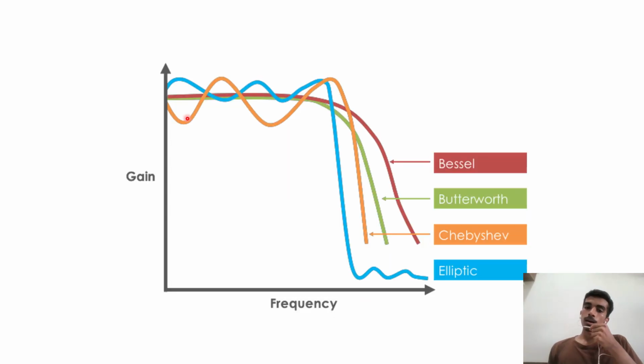As we said, Butterworth filter, why not use Bessel? We all know both Butterworth and Bessel have a linear phase response, while Bessel has a more linear phase response than Butterworth. Why do we not use Bessel? It's not used because Bessel is more linear, so it's bad at blocking unwanted background noises, which is the main aim of this project.